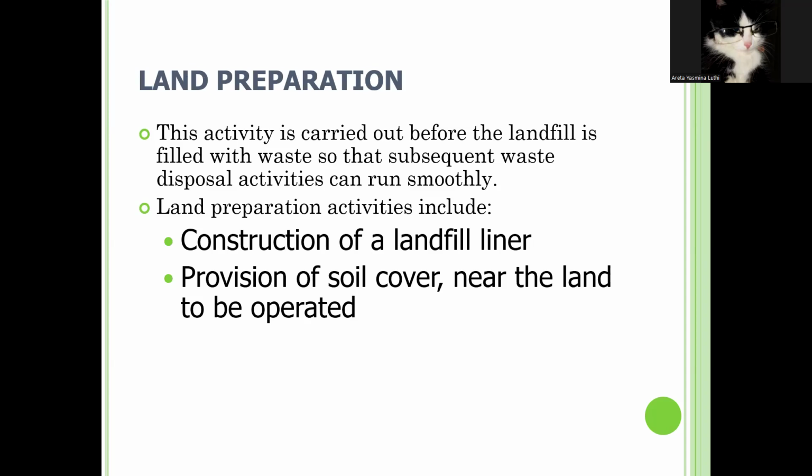And for the land preparation itself, this activity is carried out before the landfill is filled with waste so that subsequent waste disposal activities can run smoothly. And also land preparation activities include construction of a landfill liner and also the provision of soil cover near the land to be operated.